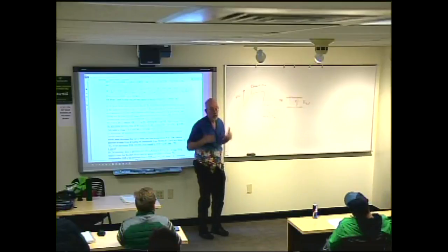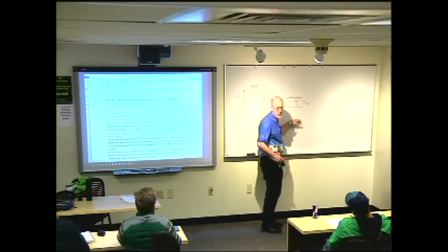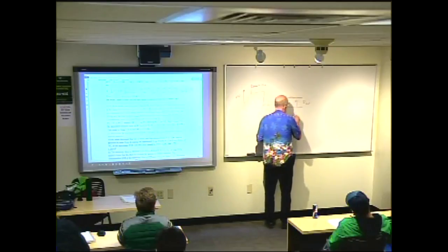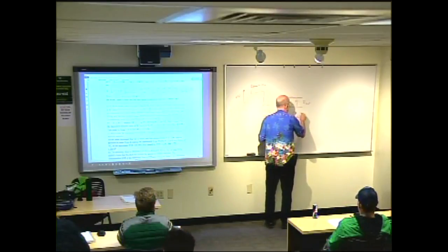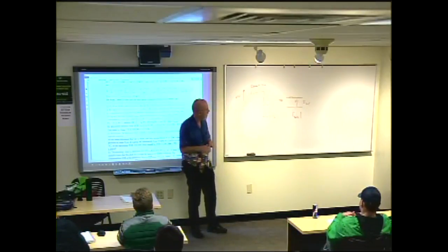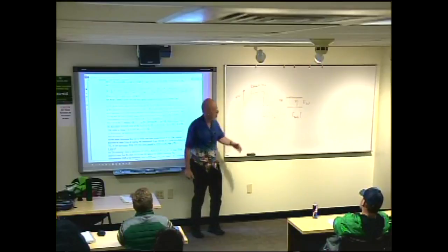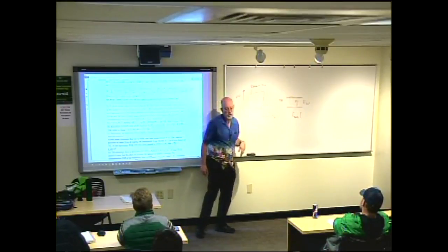You're probably used to thinking about things in the frequency domain, right? So if I have a frequency, I need to have a certain H of f so that the 3 dB frequency over here is high enough that I don't mess up my signals going through that. Here, instead of thinking about it in terms of frequency, we're thinking about it in terms of the time constants of this rise and fall.